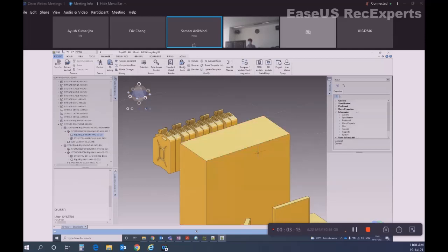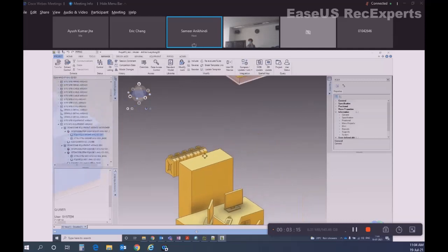So my purpose of telling this is to lock and unlock. For example, ID again. I want to keep the easting 0. So I press 0 and tab. As soon as I press tab, it will lock. But if you want to lock without entering any value, there are two ways.